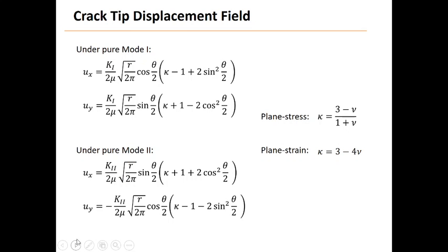On the other hand, you can also get the displacement field, because the displacement field is also part of the solutions that we derived. Because of the Airy stress function from the solution of Williams, once we have that, we can calculate the displacement field, and that becomes very useful as well, because you can measure displacements around the crack, and that is something you want to calculate.